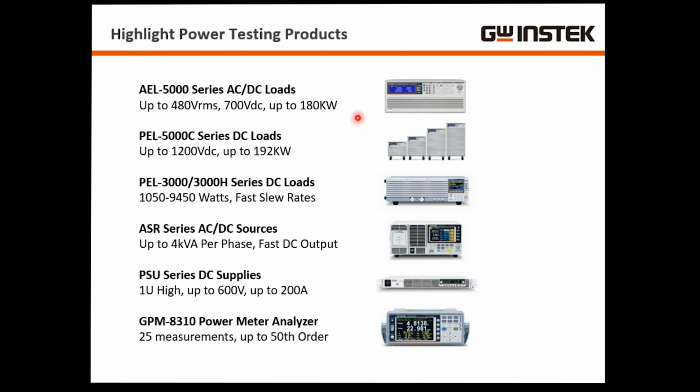These AC/DC loads can go up to 180 kilowatts. These are single-phase, but you can configure 3 of these units to create a 3-phase system. So it's very versatile in that aspect.